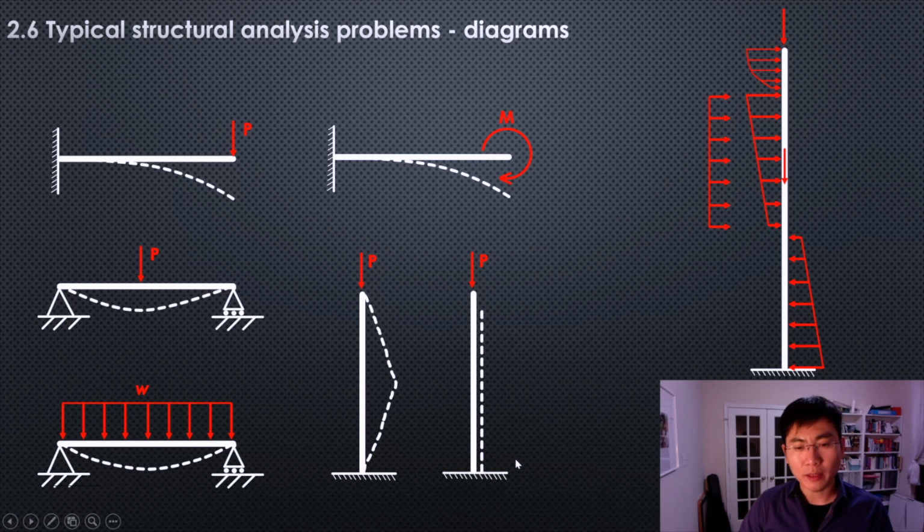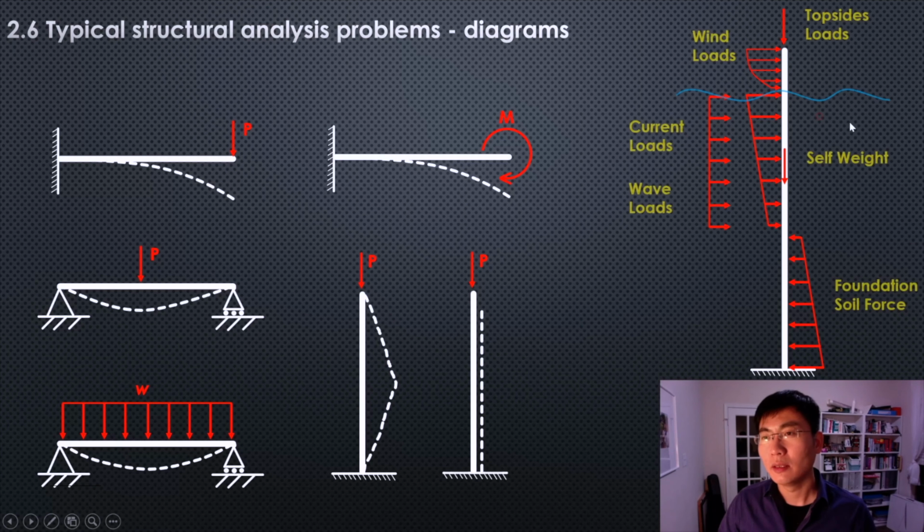Come back to buckling effect. So if the structure buckled, you have an ugly, sudden large deformation shape. Or if you have a short beam, then when you press it down, it'll just go shorter. It won't buckle like this. The picture on the right is a very interesting picture. So basically, you have a large beam supported at the bottom. It's a fixed condition. You can tell the top is a free boundary condition. So what is this? Well, I don't know if you guys are surprised.